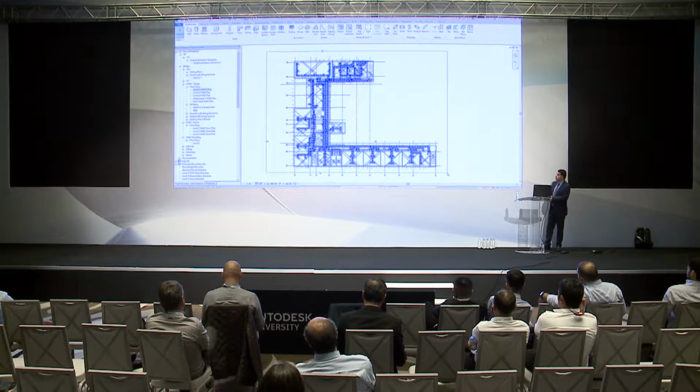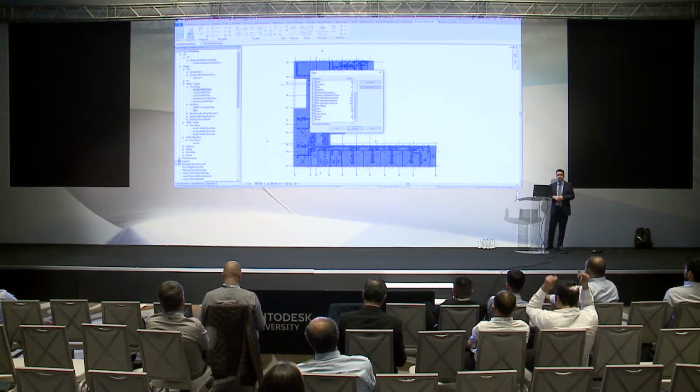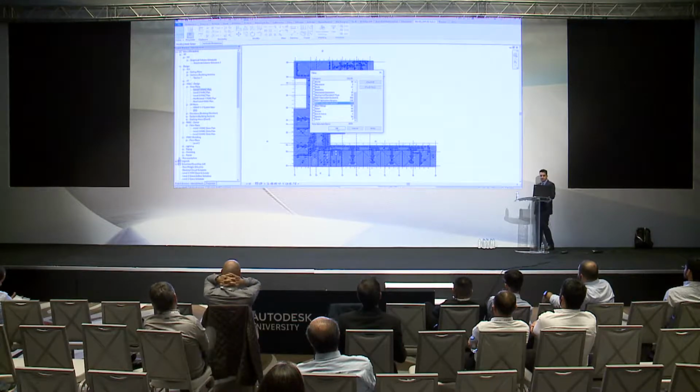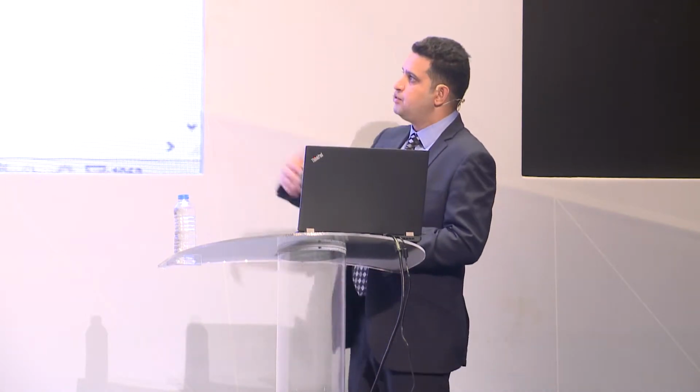Now what I'm trying to do here is select everything and export all the content which we created or converted to fabrication, all the ducts, the fittings, and everything I just said, and I'm going to export them. Why am I exporting them? Because I want to have the estimation. So I'll export from Revit. We call it a fabrication job. So this will save to a file format we call MAJ. And that is it from Revit.